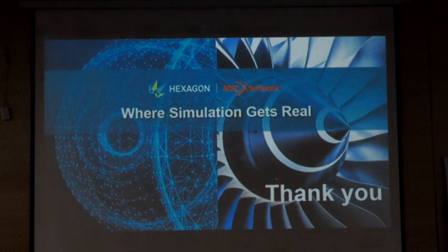So the software can be used as artificial intelligence, right? Yes. Suppose I am sending my original design to optimize, will the software be able to identify whether the design has scope to optimize or not? Yes. Before the simulation, it will identify. It is an iterative way, so it will keep on running. When the last iteration and the next few iterations have seen no material reduction, it will stop, saying that there is no scope for further optimization.